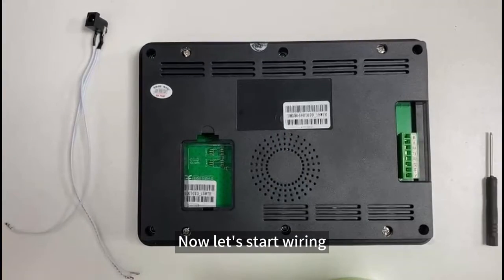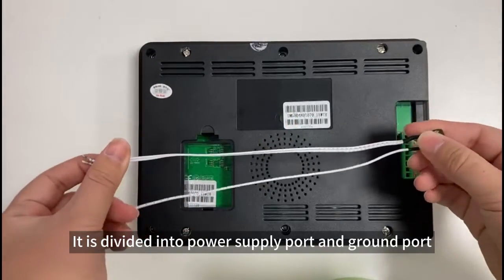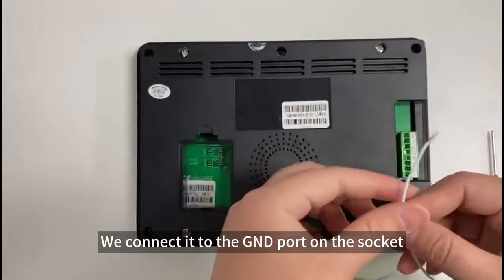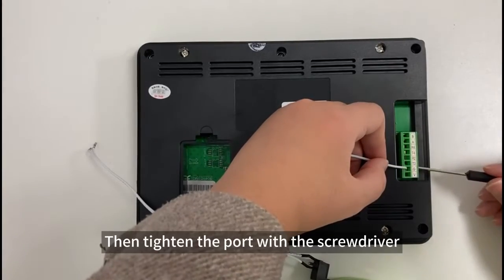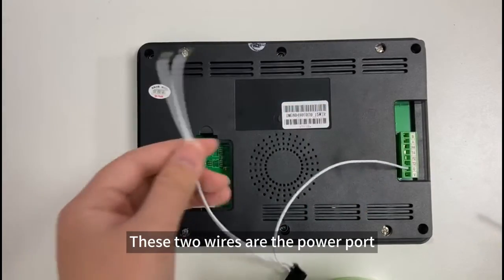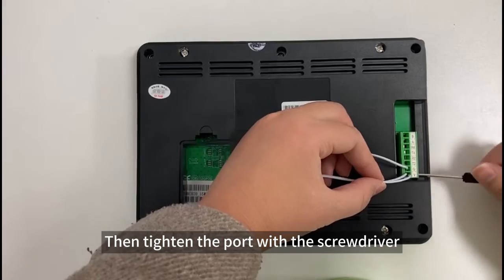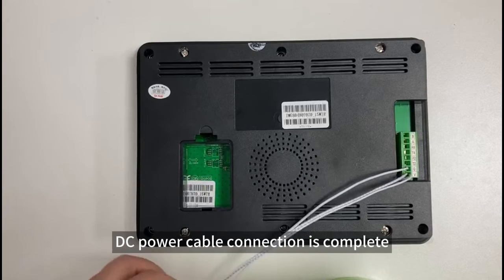Now let's start wiring. This is the DC port. It is divided into power supply port and ground port. This single wire is the ground port. We connect it to the GND port on the socket. Then tighten the port with the screwdriver. These 2 wires are the power port. We connect them to the VIN port on the socket. Then tighten the port with the screwdriver. In this way, DC power cable connection is complete.